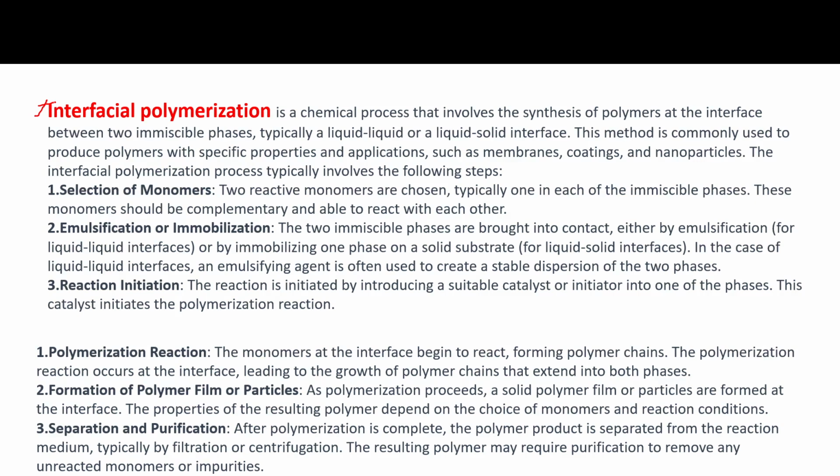With increasing molecular weight the polymers become more sluggish, that is, the reaction rate is slow and we cannot reach higher molecular weight, because the viscosity increases with molecular weight. So there is another technique, interfacial polymerization, where we can get a higher molecular weight.